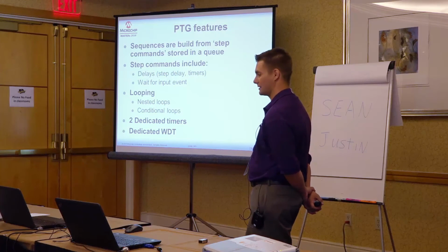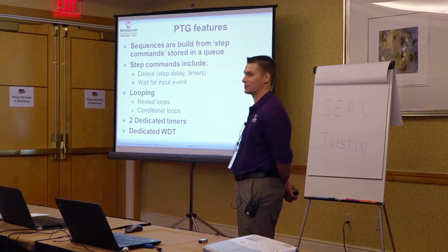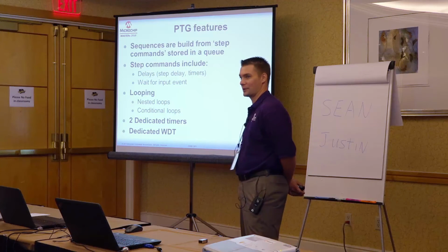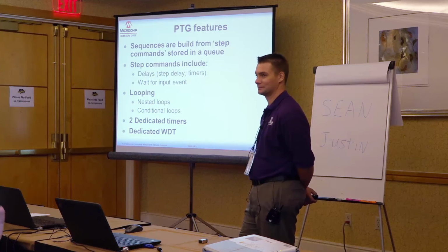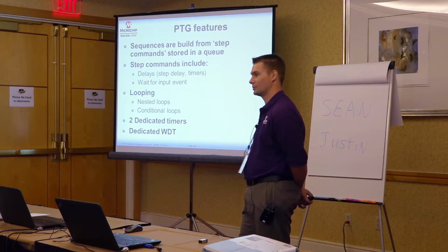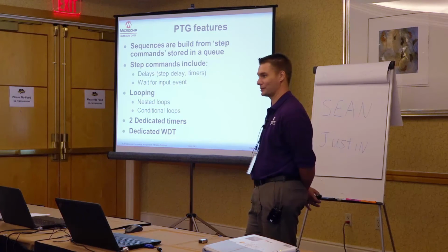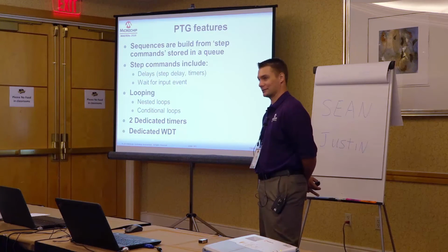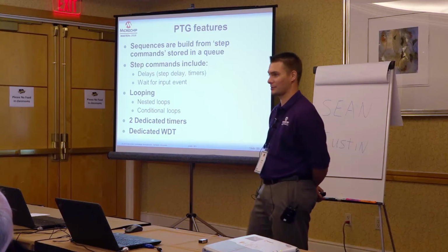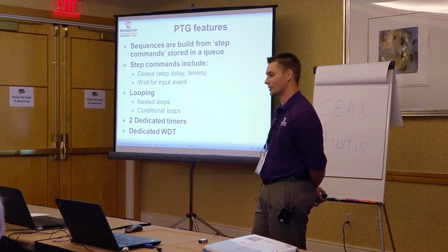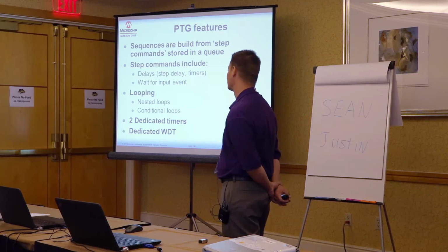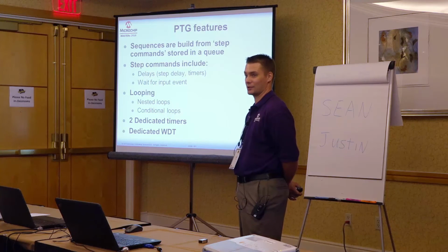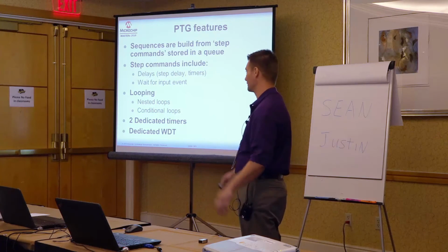It also has 2 dedicated timers, which is an important feature for doing delays in that you don't need to use one of the other system timers. So, does anybody know why you wouldn't want to use maybe Timer1? Well, usually you'd have to use an interrupt to get the overflow or a compare from that. Since the point of these classes is to be core independent, this one has its own timer built in, and you don't need to use any code in interrupts to stitch these solutions together. It also has a dedicated watchdog timer in case you never get an input or something has gone wrong in your system.